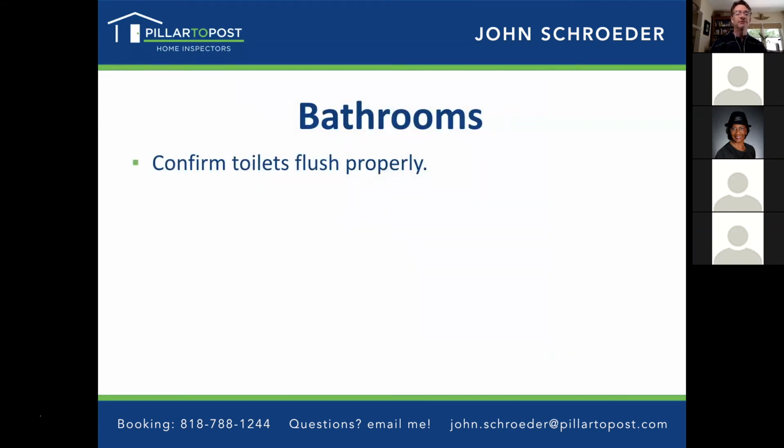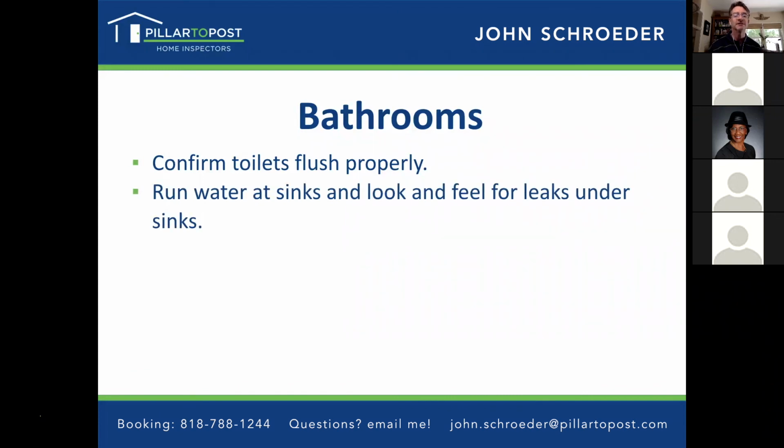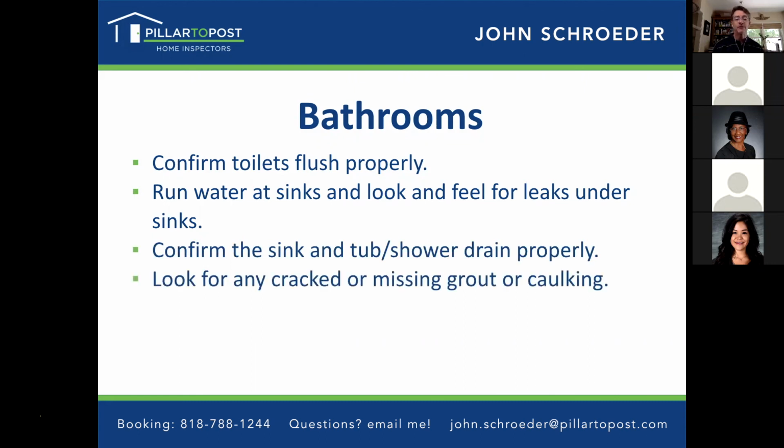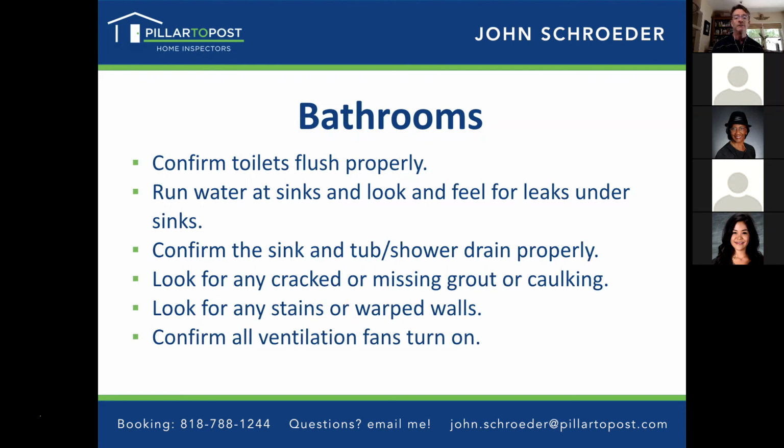Bathrooms, you want to make sure all the toilets flush properly, run water at the sinks, and look and feel for leaks under sinks. Confirm the sink and the tub or shower drain properly. Look for any cracked or missing grout or caulking. Look for stains or warped walls. Confirm that all ventilation fans turn on.